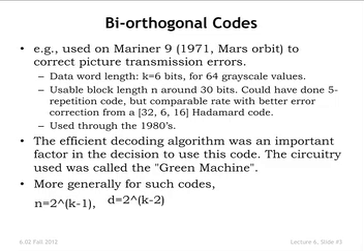It turned out that with this particular Hadamard code, you could actually get the same data rates or comparable data rates. Let's see, what would the data rate be? It would be k over n, right? 6 over 32. But with much better error correction properties. So let's see, how many errors could you correct in this code per block?